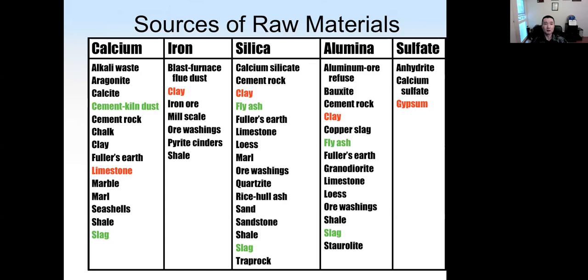So we do not have enough time to mix the concrete, transport the concrete from the plant to the job site, pour the concrete, finish the concrete, and so on. We need at least 2 to 4 hours for this process. So we need to slow down the chemical reaction. Gypsum helps us slow down the chemical reaction of clinker. Again, we will talk much more about this.